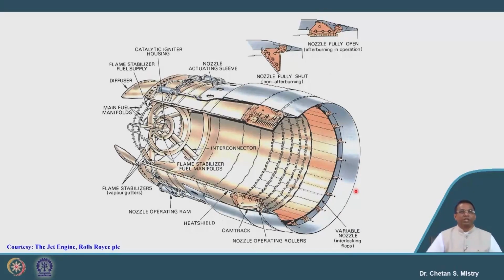At that velocity, the combustion will be very difficult, we know that logic, and that is the reason why we need to decelerate the flow, and for the deceleration of the flow, we are looking for the diffusing passage. So we are adding a diffuser.